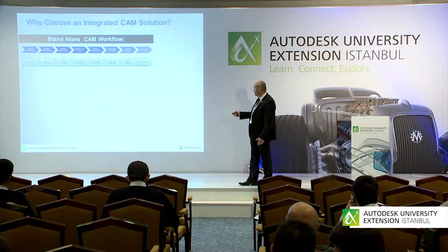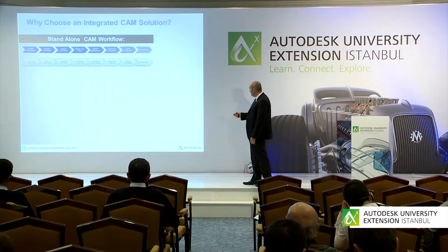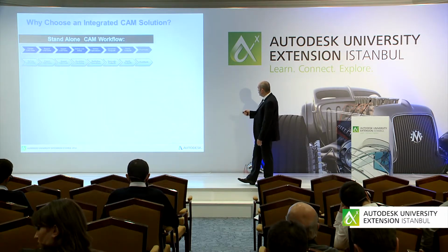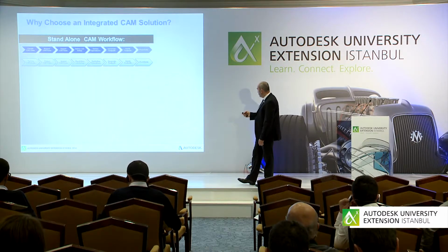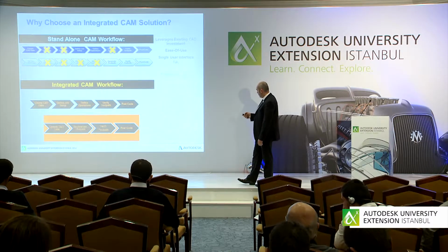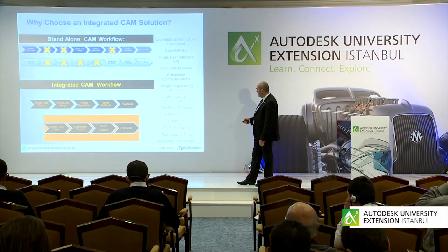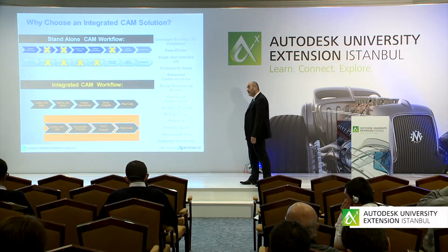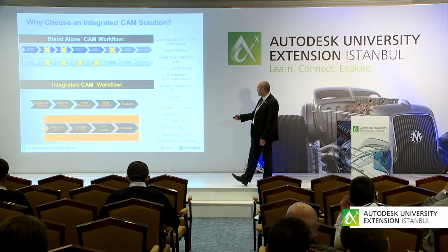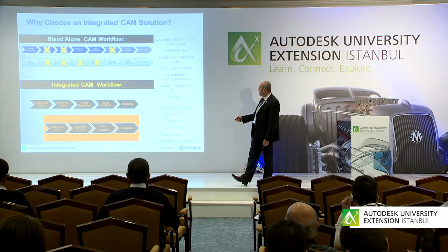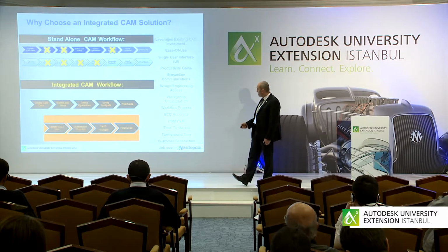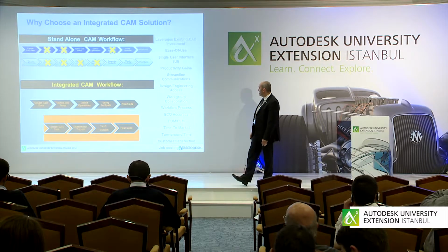If you change something, maybe you have to update the CAD data, export, import again, sometimes redefine operations, job, generate toolpaths again, and so on and so on. And if you use an integrated workflow, you can eliminate almost half of them. As you can imagine, create CAD data, which is really easy if you use Inventor. You can also import this data. Define on an existing CAD model a job setup, define strategies to remove the material, verify, simulate the toolpath, generate the post or the NC code, that's it.